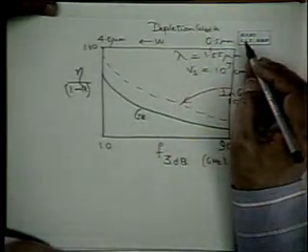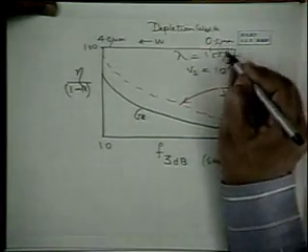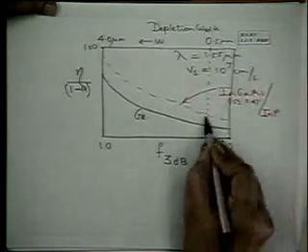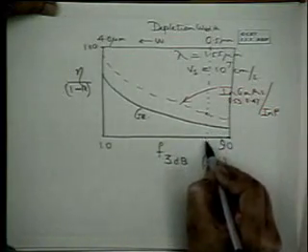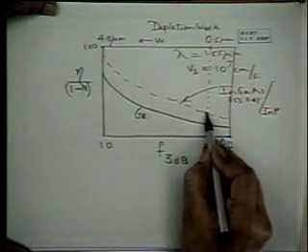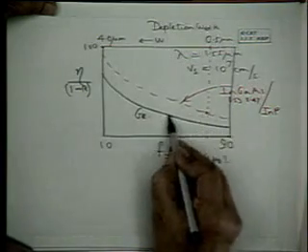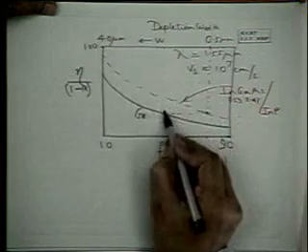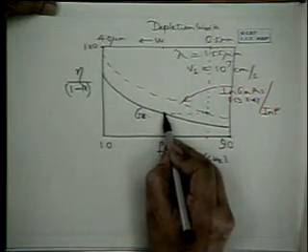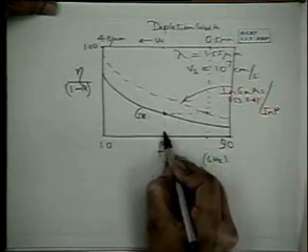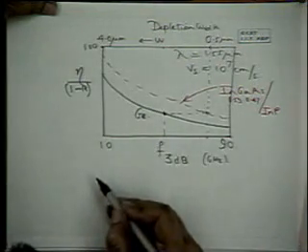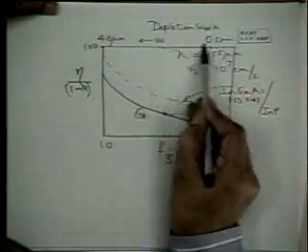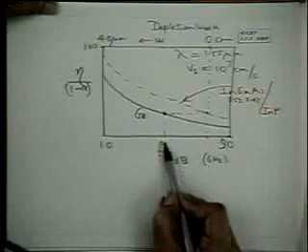So, say for 0.5 micron depletion width in InGaAs, we have this quantum efficiency and this value of F3dB. If you want this same value of quantum efficiency for germanium, then we need a much higher depletion width. We get the same quantum efficiency, but then the F3dB is less. That is because germanium is an indirect gap semiconductor, so alpha is lower at a particular wavelength. To compensate for that you need a higher value of W, and if you have a higher value of W, then F3dB comes down.